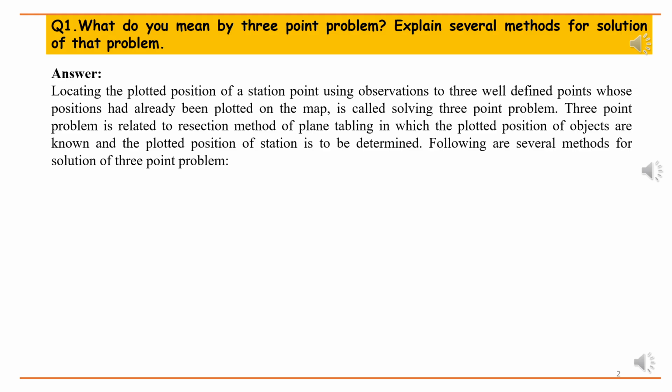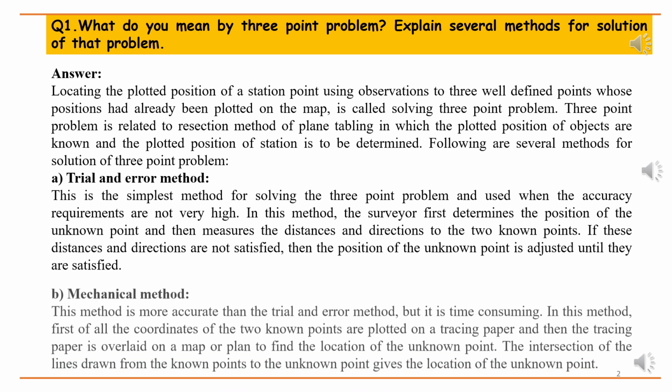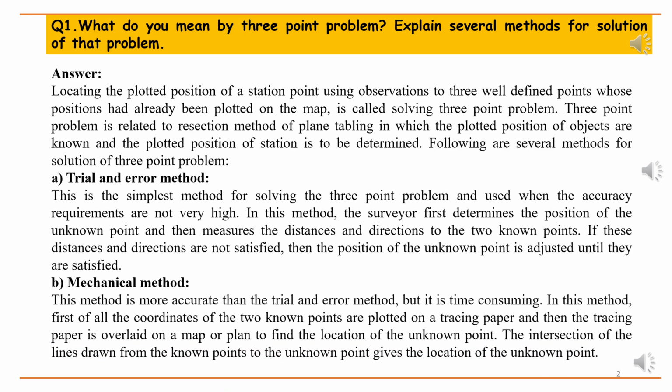Three-point problem is related to the resection method of plane tabling. A. Trial and error method. This is the simplest method for solving the three-point problem and is used when the accuracy requirements are not very high.